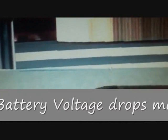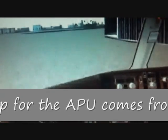First, we go to the overhead, turn on the battery, and we switch the APU knob into the start position, and you'll see these indications: fault, and then run. Now, all the fault means is that the APU is not actually on or online. What happens when you turn the APU switch into the start position is two things. First, the battery voltage drops, and then the APU inlet door opens. Once the APU inlet door is completely open, then it activates the starter turbine in the APU and helps it start spool up. Now all we have to do is wait.